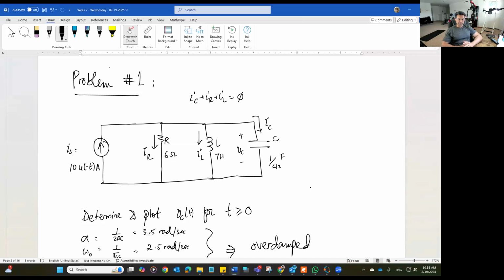It's a natural circuit, of course, IS is gone. You have different variables on the circuit. In terms of those variables, how are you going to write down IR? Wouldn't IR be equal to negative IC minus IL? No, we already used that equation to write down IC. What is the voltage across R? In terms of the variables that you see on the circuit, what is the voltage across R?